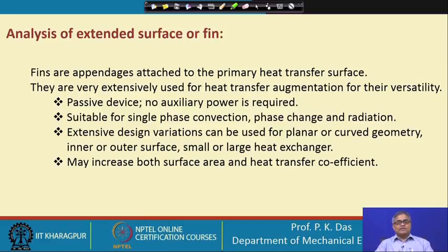The heat transfer may increase by the fin design. Definitely we are increasing the surface area, but by our innovative design we can sometimes increase the heat transfer coefficient also. Sometimes, by a good design in condensation, we can promote the drainage of the condensate film, which is very important. Then as it is a passive device, it will have the features of a passive device. That means it is highly reliable, low maintenance, all these things are there.